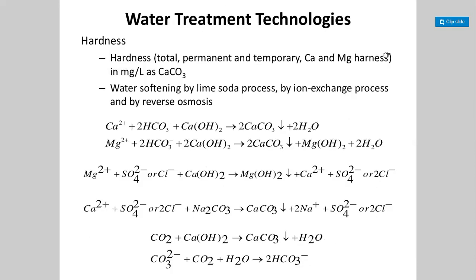Here, water treatment technologies address hardness: total, permanent, and temporary, calcium and magnesium hardness in milligram per liter as CaCO3, and water softening by the lime soda process, by the ion exchange process, and by reverse osmosis. These are the reactions used in new water treatment technologies.